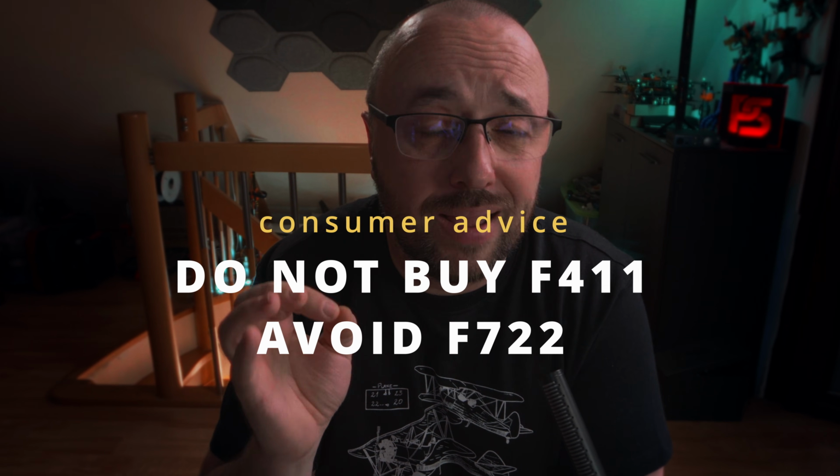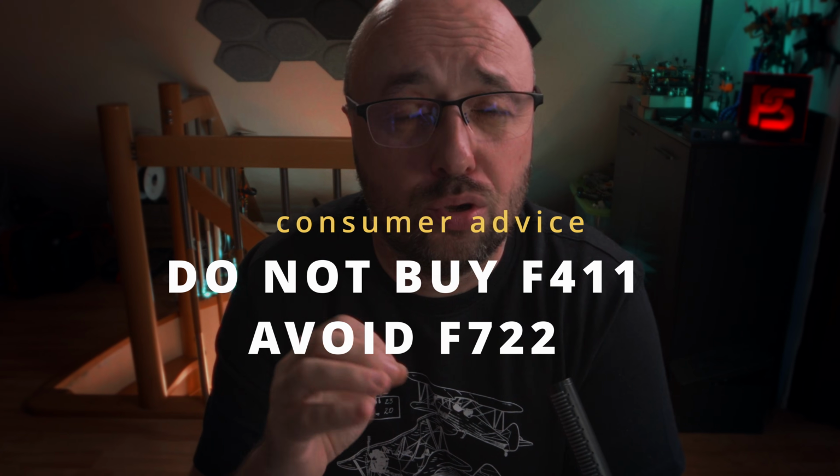Which version of the STM32 flight controller should you buy? Well, let's say it like that. Do not buy F411s and rather do not buy F722s. My personal advice is to go with F405, eventually with F745s, and if you want the best of the best, the biggest and the best, then go with the H7. But F411 and F722, although they are the cheapest, do not buy them. You might wake up in a situation when in a year or two there will be no software you can use with them anymore.